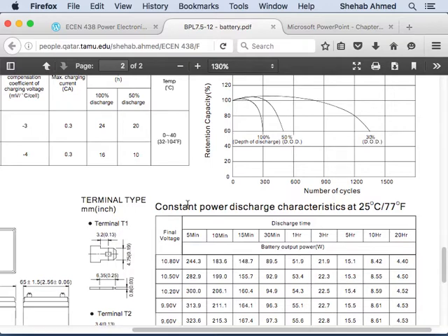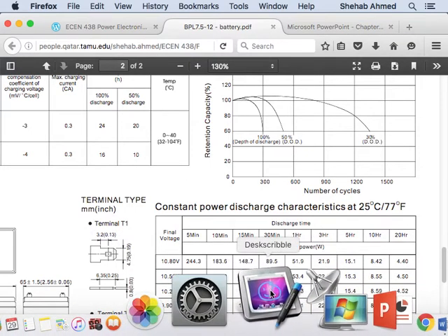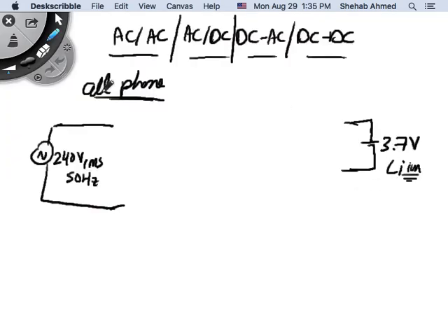So we won't get into that, but we got into this because we were trying to talk about the lithium-ion battery. So here we just said 3.7 volts for simplicity, right? But we would actually have to go in and figure out, for you to develop a converter to charge or discharge this, you know that this is not a fixed 3.7 volts anymore, it's a variable voltage. So you have to make sure that you can develop something that's variable.